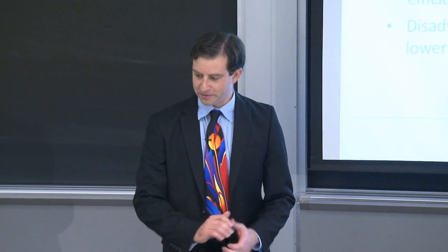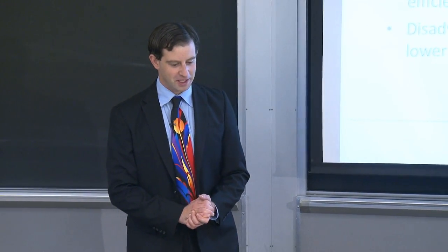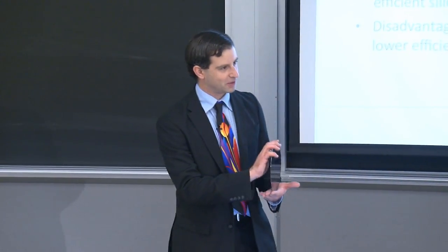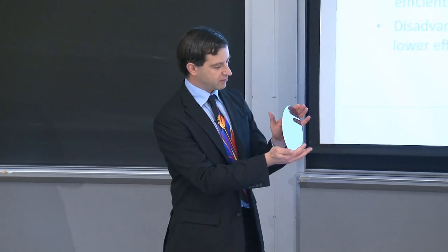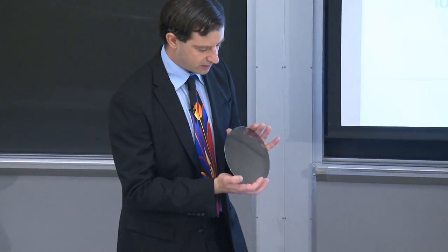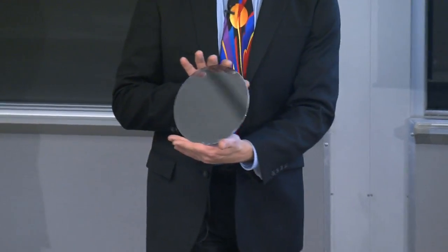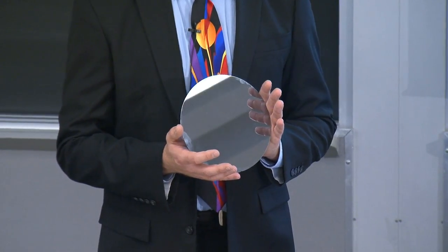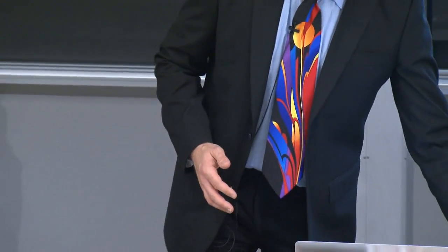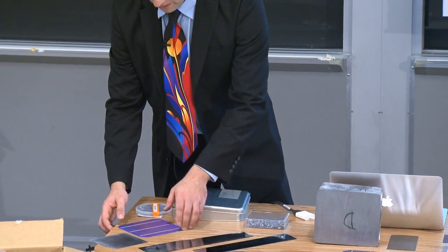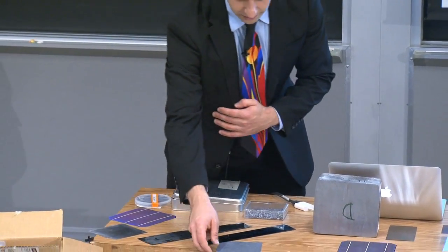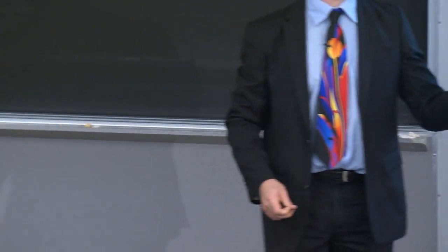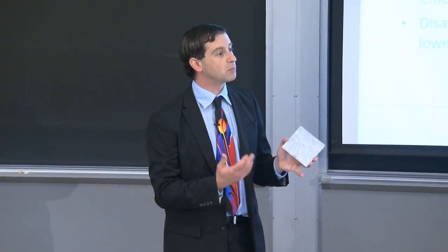But that gives you an idea of how well purified silicon can be and how well controlled it can be as well. During integrated circuit fabrication, which uses this ultra-high purity silicon to produce very nice single crystal wafers like this one right here, the investment per gram of silicon can be on the order of a few tens or even low hundreds of dollars per gram of silicon and still turn a profit. But in a solar cell, on the other hand, you can invest at most a few tens of cents per gram of silicon. This because the solar cell has to compete against bulk power. That's its competition coming out of the wall right over there. So the solar cell has to be able to be produced much more cheaply.